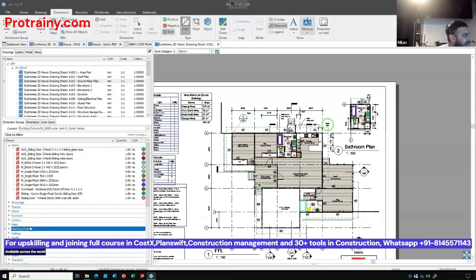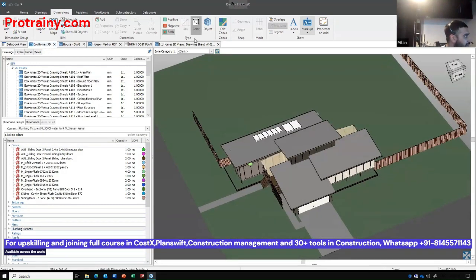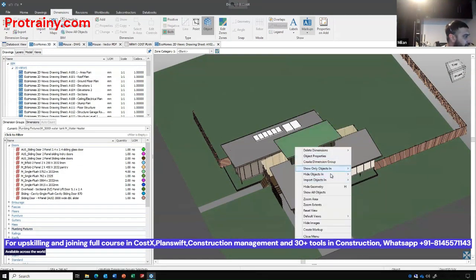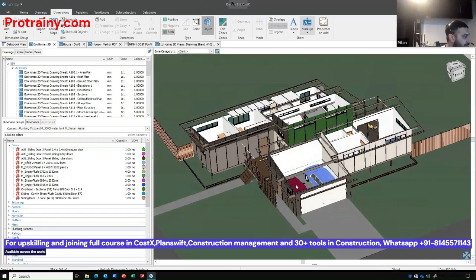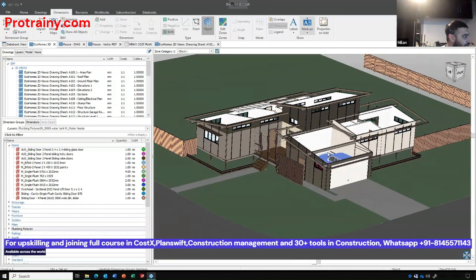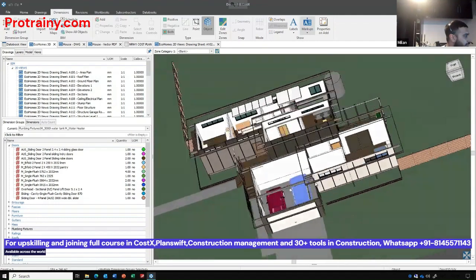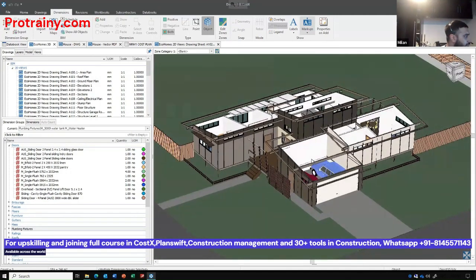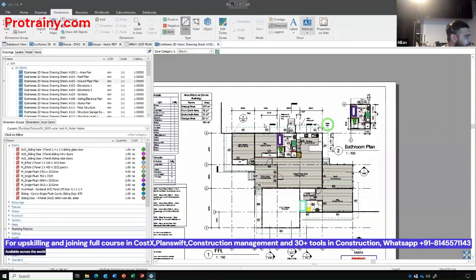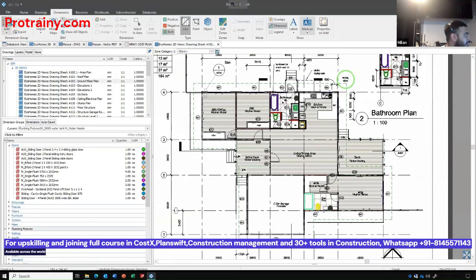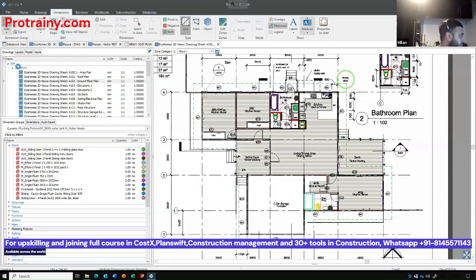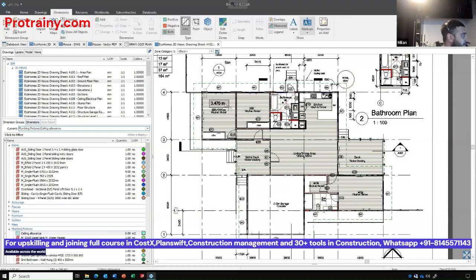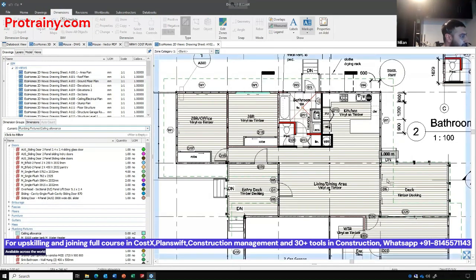And it allows you to measure things that aren't modeled, because there's lots of things like timber skirting. And I remember from this example, if we look here and we hide the roof, you can see there's no ceiling object. So we have a house, but no ceiling. We just have roof. So we can come back to here and we can make an allowance and say ceiling allowance. And we can come in here and we can use our regular line mode.